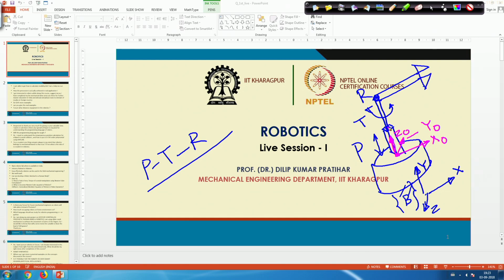Now, comes here, this particular joint is a twisting joint. So, z is along this particular direction. So, this is z 1, and let me assume that this is my x 1, and z cross x is nothing but y 1. Now, this is a revolute joint. So, z is in this particular direction; I consider opposite to this as the z. So, this is your z 2, and let me consider this is your x 2, and z cross x will be my y 2. And the same coordinate system you copy it here. So, this is z 3, this is x 3, and this is your y 3.